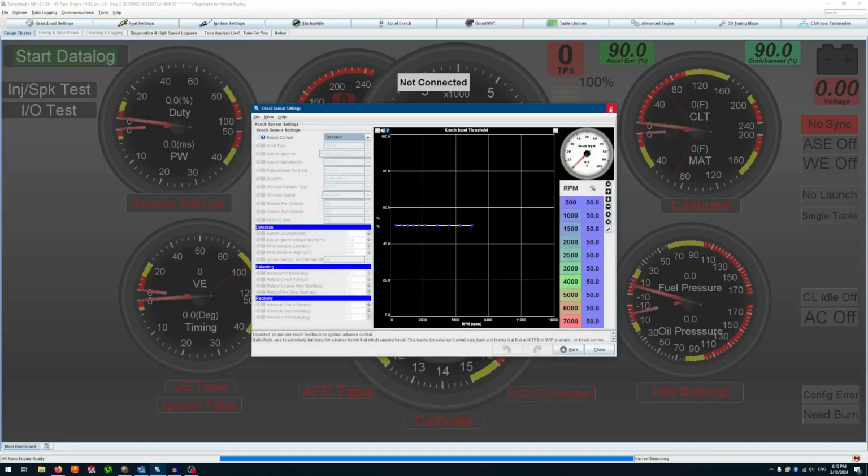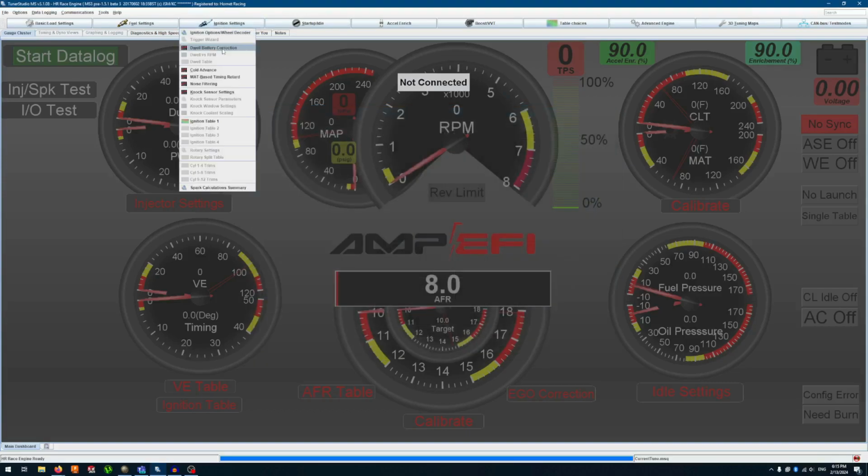Knock sensor. We don't use a knock sensor, but why don't we? Isn't that a good thing? No. Well, yes, but we don't need it. The reason we don't need it is because we have a restrictor. Therefore, we are not filling the cylinders with enough air to reach a high enough cylinder pressure to require a knock sensor, because our engine does not and will not ever knock. Our cylinders simply don't have enough air in them to require it.